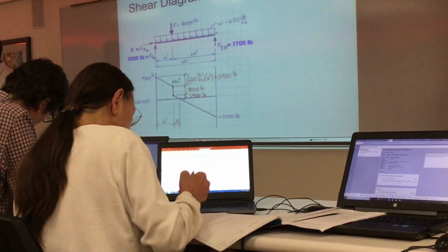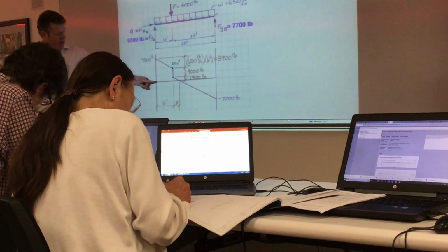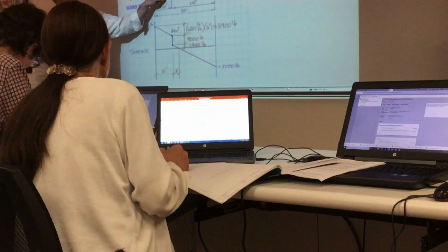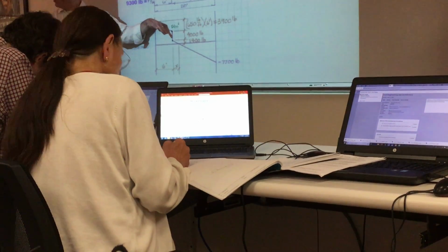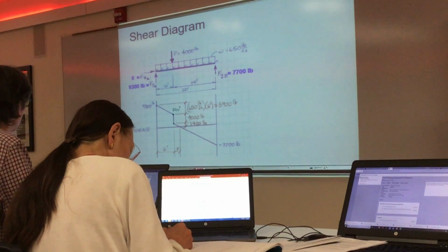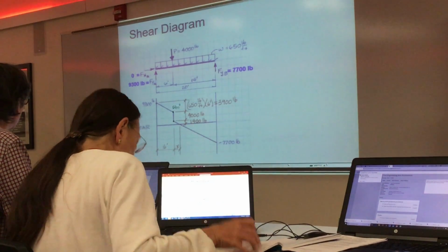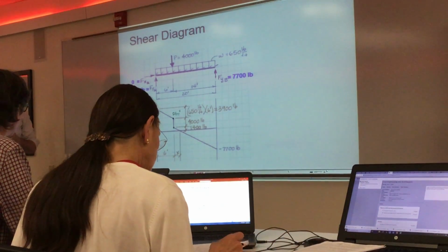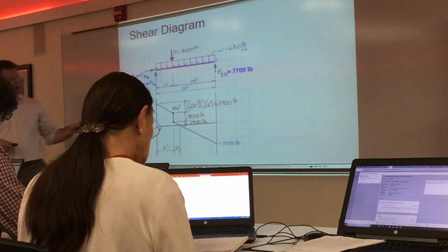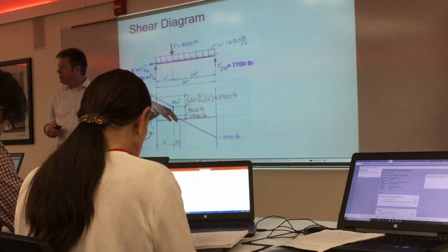So why is it on that diagram your spikes are vertical, but this one's sloped? You mean between? Yes. Because when I've got a uniform load acting on it, it's pushing it down uniformly between the members. In that one over there, I've got nothing in between, so it just stays constant, because there wasn't a W, a uniform load, given in that one. Correct, it's just the 2 point loads. And point loads only make spikes up and down like this. Uniform loads make slopes between the points.